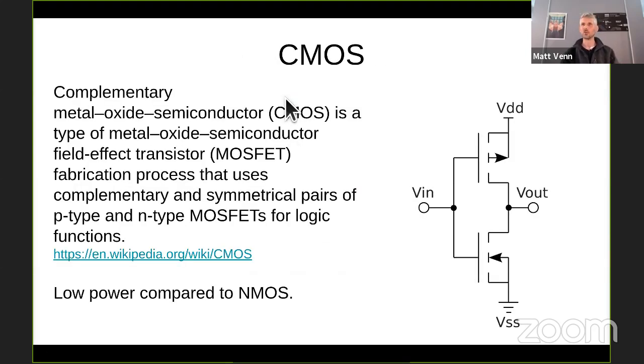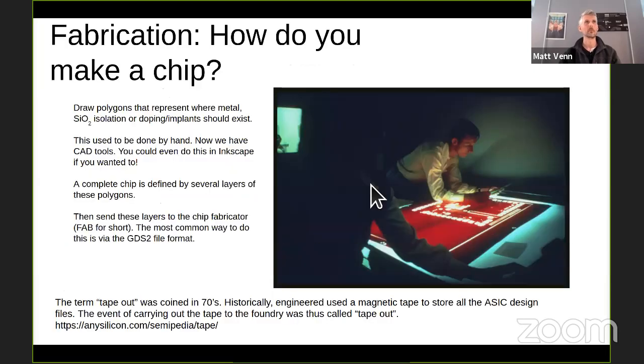So what we do is we put an N and a P channel together so that the P replaces the pull-up resistor, so that when the P is turned on, it's pulled up, and when the N is turned on, it's pulled down. Putting the two together in this complementary style is called complementary MOSFET, or CMOS. The big reason to do that is for efficiency.